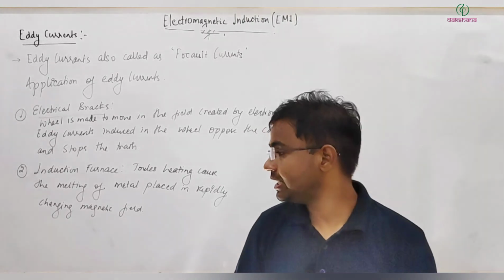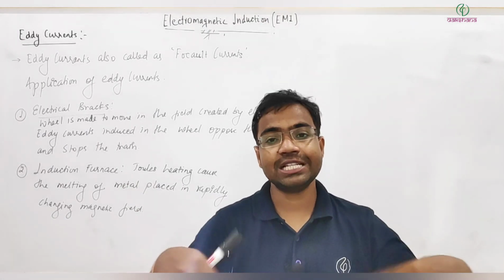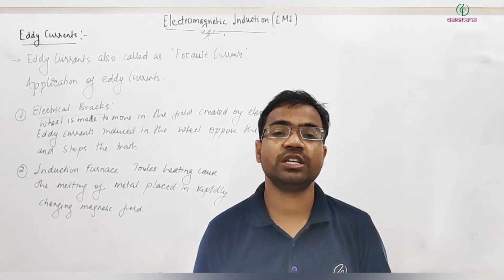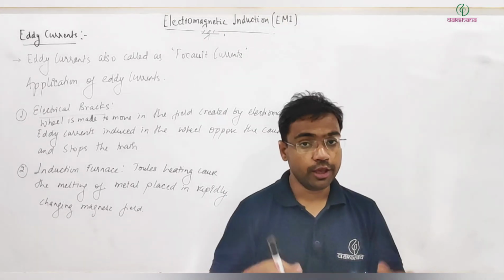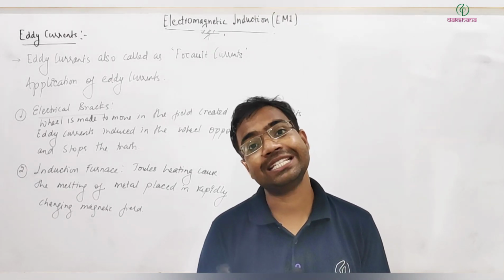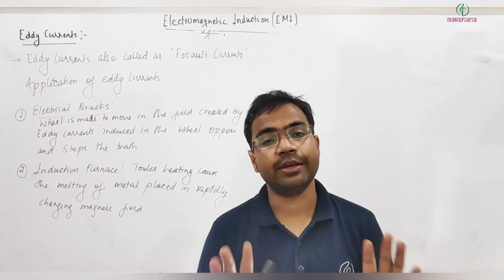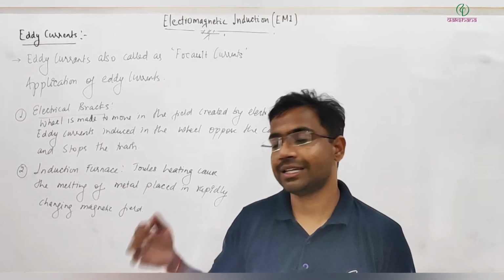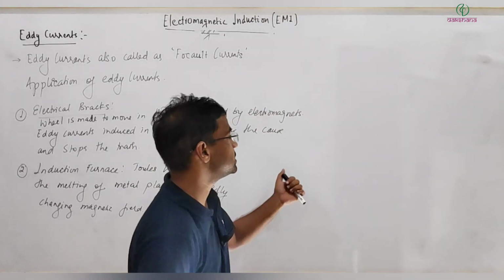For that system, we have eddy currents, and these create a brake. Some wheels pass through a changing magnetic field, or an electromagnet creating a magnetic field, when we want to stop the train. When they pass through it, the changing flux linkage produces eddy current, and this eddy current opposes the motion and applies a brake on the magnet trains. That is how the electrical braking system also works, based on eddy current. So this is all about eddy current.